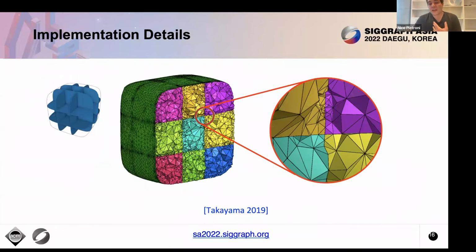Obviously there are some particularly challenging implementation details, such as how you propagate or split internal tetrahedral elements to create your mesh. Always consider that when we talk about Hex-meshing, sometimes we start with a triangle mesh. Most of the methods start with a tetrahedral mesh, given that it's much easier to derive. We don't need a super good quality tetrahedral mesh, but it's better. Some methods require an already volumetric domain, like this one.